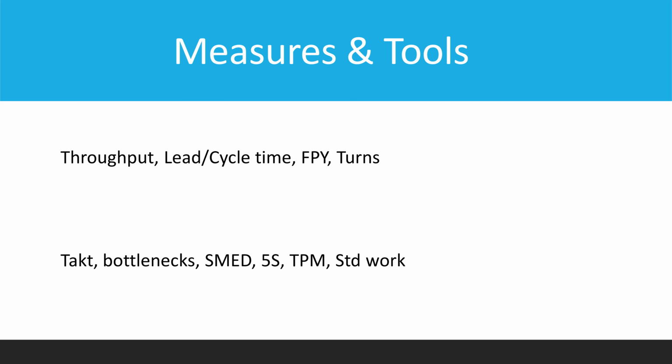I calculate takt time as available production time divided by customer demand, and I balance work to meet that pace. I look for bottlenecks by measuring queue build-up, uptime, and changeover duration at each step. I raise availability with basic autonomous maintenance, and I schedule planned maintenance when demand is lowest. I stabilize work using standard work and visual controls so that variation is visible early.